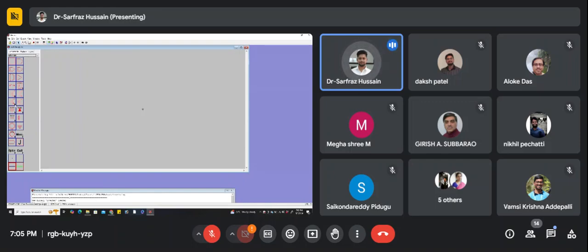Now onto the left, you see a black arrow. Once you click on that, you get these many options. You can use a PFET, an NFET, an NPN transistor, a PNP transistor. You get a lot of options, and in NMOS also you get a lot of options. Out of all these options, we'll select this NMOS first and place it somewhere here. Now remember this, there are four terminals here. We want a four terminal NMOS. Whenever you go for analog design, always use four terminal NMOS and PMOS.